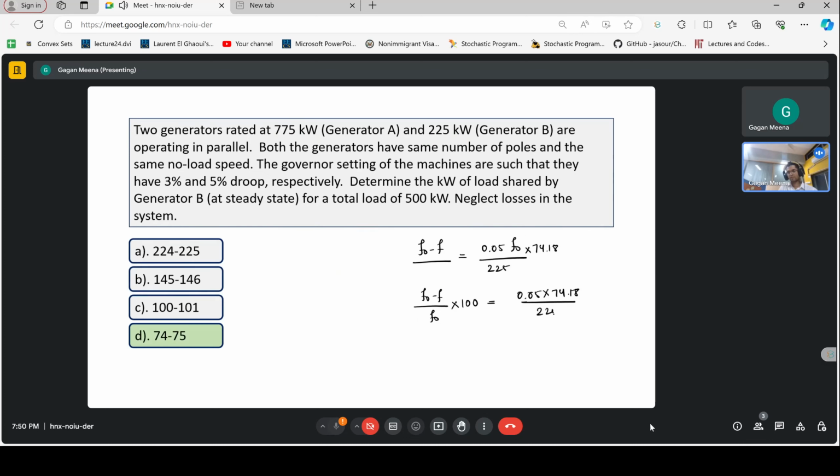Make it 11. So load frequency control. For an isolated generating system with local load shown, it is observed that delta PL is minus 0.15 per unit. It brings about delta omega of 0.25 per unit.